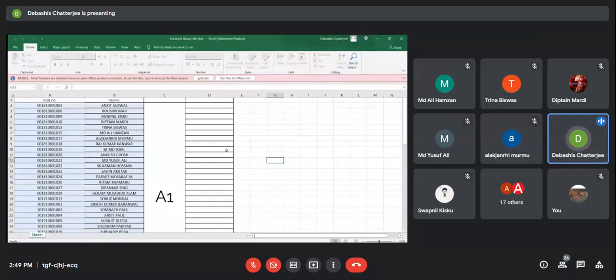I'm always telling you it is tentative because it may not happen that you get the design at the same power factor, but this is tentative. You can start with that. And temperature is same, 45 degree above ambient. You design for minimum weight. Minimum weight means the machine weight for your design should be minimum. It will meet all the parameters, but you have minimum weight.